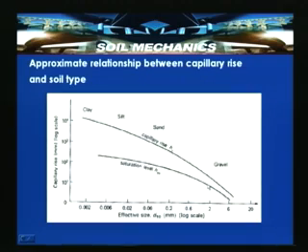This particular property is also considered wherever we want to prevent or arrest capillary action. When you do not want this capillary action to prevail, then we use gravel or sandy soil materials as capillary cutoff materials. They can act as capillary cutoff layers, and this is particularly adopted for man-made structures, so that the water does not remain saturated, because if it remains saturated, there can be changes in the properties of the soil.